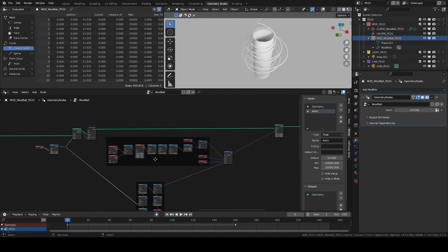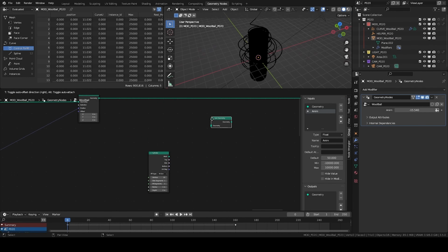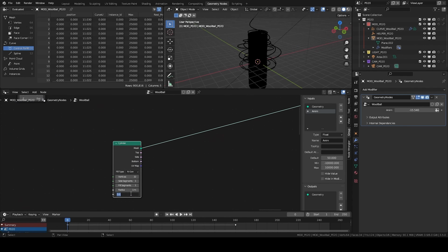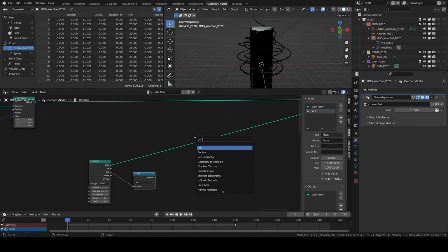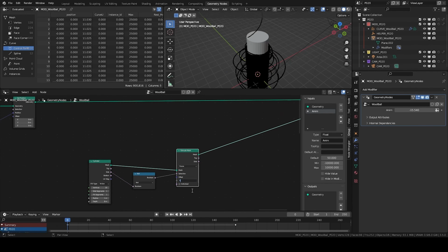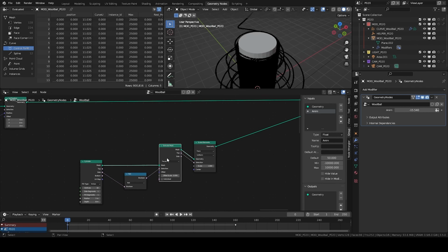I go back to the end of the line, and there we're going to create our cylinder, a primitive cylinder, a join geometry to be able to see it. Make it the size of our wire cylinder roughly, so it's about 8, because when I do a Boolean math, I take the sides. I say, everything except the sides will be extruded. We're going to extrude only the top faces, and in fact, we extrude them, but they won't move. Behind it, I'm doing a scale element. I only plug in the faces that have been extruded. So the top face, that's just been extruded.